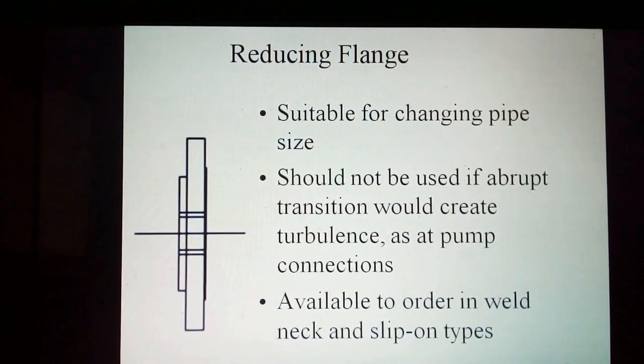Reducing flange is suitable for changing size but should not be used if an abrupt transition will create turbulence, as at pump connections. Available to order in weld neck type and in slip-on types.